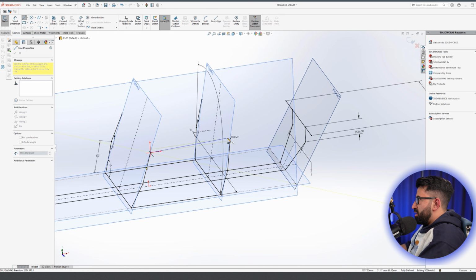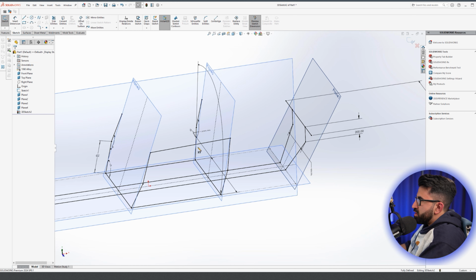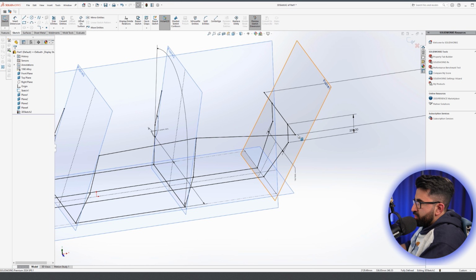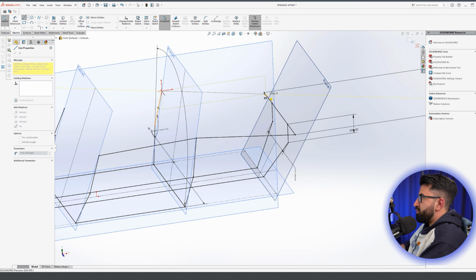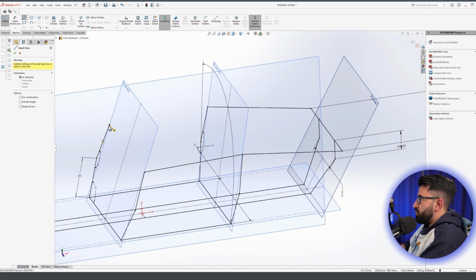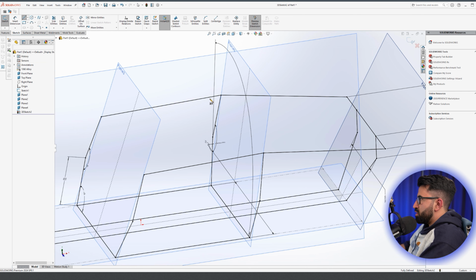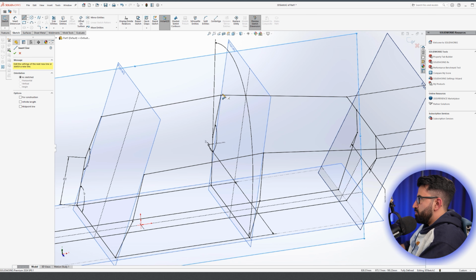Now at this point, because I have my fully defined sketch, I don't need to work in the split view, because once I connect this line from one fully defined point in black to another one, this line comes out fully defined. I don't need to worry about whether it's being added in the right direction or not. When I'm connecting already defined points together, it's already taken care of and we have no issue whatsoever. So let's connect these two.